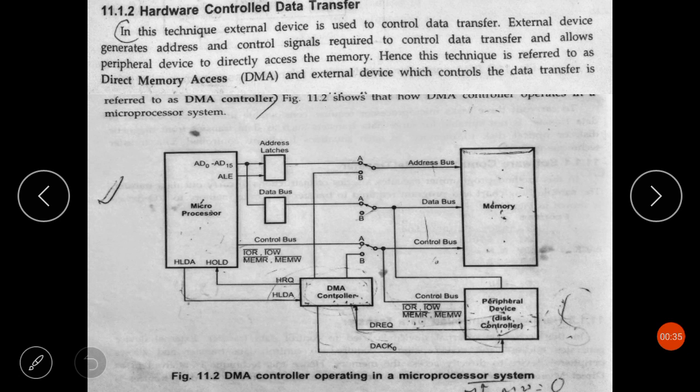For doing this we have used program instructions. So far, for microprocessor based systems, we have used program instructions to transfer data from input output device to memory, or from memory to input output device. To transfer data using this method, the microprocessor has to fetch the instruction, decode the instruction, and execute the instruction. Only then the data gets transferred from input output device to memory, and vice versa. To carry out these tasks, the microprocessor requires considerable time.